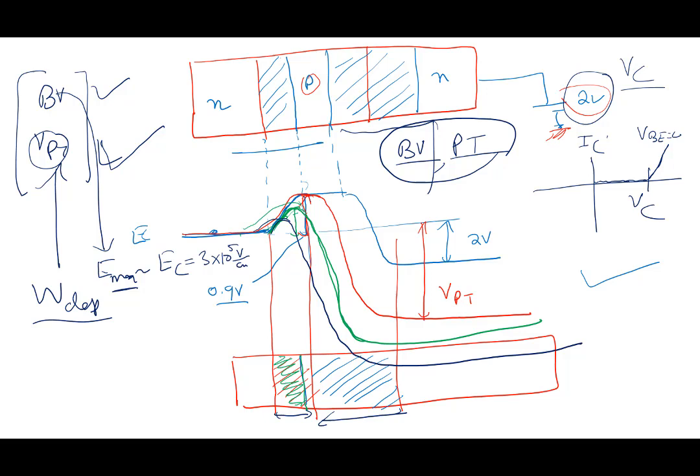So your ability to solve Poisson's equation in a depletion region and do these calculations is very, very important, very fundamental to all semiconductor devices. Calculating depletion widths, calculating maximum electric field, calculating capacitance, all these things are very basic things that all of you should know how to do. All right, so I'm pointing out in the design of the bipolar transistor why these are important.